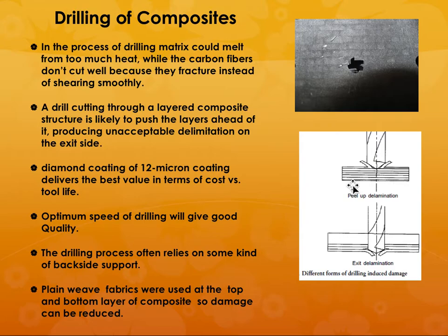You may use a different kind of weave on the top and bottom surfaces so that it becomes easy for you to drill right through the whole composite stack. So it's always something to be noted.